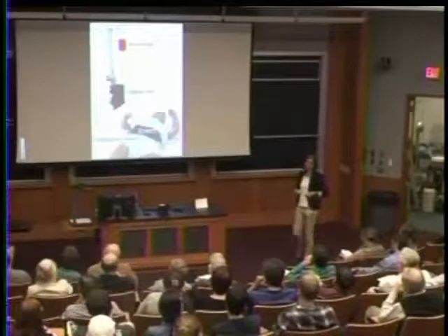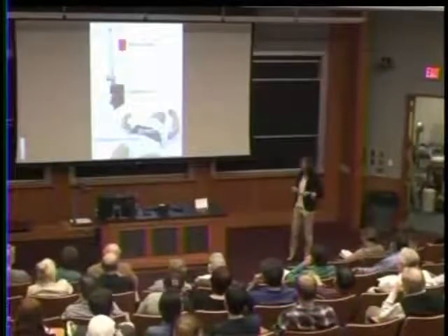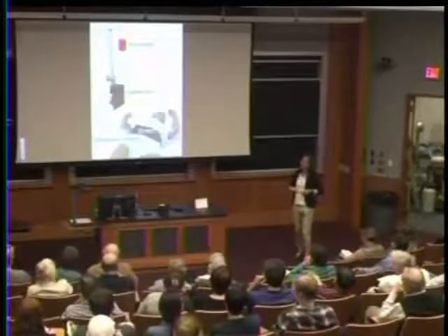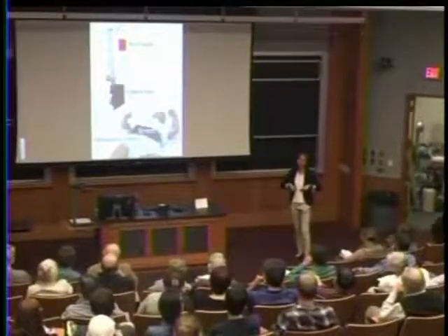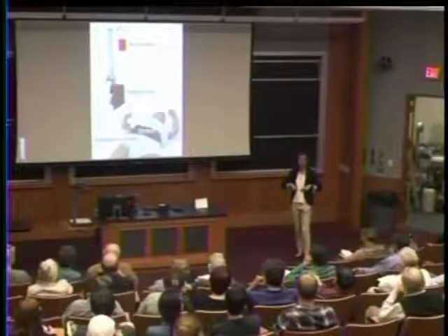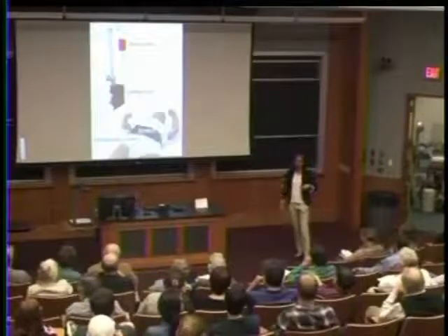We started with a stretch sensitive resistor, but now we've actually moved to an optical sensor because it has better long-term stability, and it detects when a baby stops breathing. But it incorporates two little piezoelectric motors, and if the baby stops breathing, you don't have to wait for the nurse. You just stimulate those motors, and that's enough to get the baby breathing again.